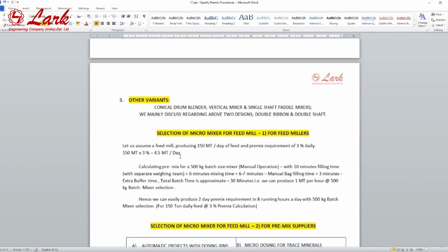If we want to produce mash or breeder feed from the same hammer mill, even if we use a coarse screen, for example a 6 or 7 mm screen, at that higher tip speed we will get 15 to 25% fine dust of below 300 microns. That is not suitable. Maybe more than that. Yes, exactly. Maybe 25-28%. That is not suitable for the breeder mash or the layers.